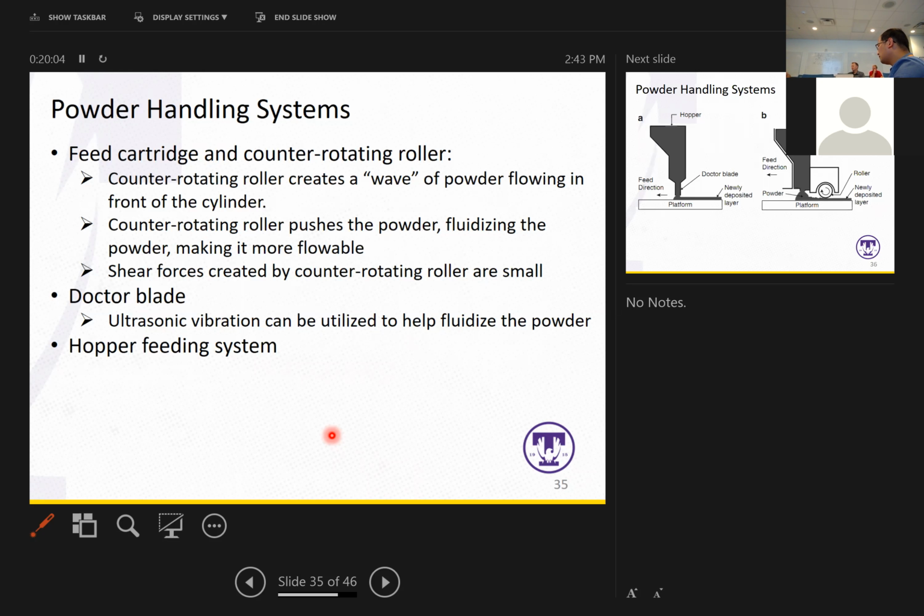So you could calculate your way through that. But say for a lifting device, right? If you wanted to make a lifting device that picks up parts, yeah, you're bounded by codes, and the lifting device code requires that you design your fixture with materials that have properties agreed upon by consensus standards, and there's no consensus standard that says you have this minimum tensile strength for some AM process right now, because there are so many variables that go in.